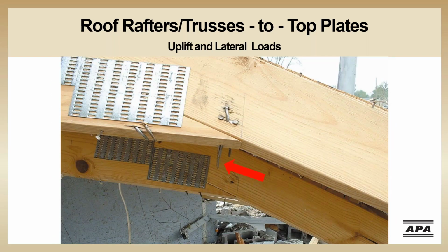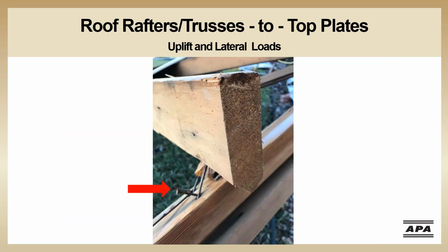At this building in Missouri, the roof trusses could be seen on the ground after a wind event. The only attachment of these roof trusses to the top plates was toenails. The strength of this connection was insufficient in this instance. The toe-nailing in this roof rafter connection simply cleaved the framing member during a wind event, leaving the nails intact in the top plate.